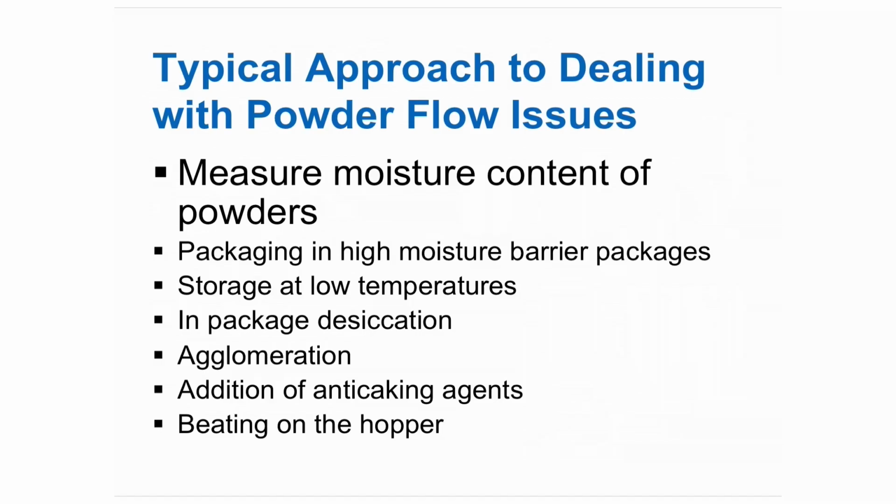You may store it at low temperatures, since again, keeping in mind the idea that it's moisture and temperature along with time that have the impact. So if you can store at low temperature, you could eliminate the temperature effect, but of course that can be costly as well, to have special storage conditions. You might include some sort of a desiccant in the package with the powder material that preferentially takes up the moisture and keeps it away from the powders that would start to cake and clump. And you can do this also with anti-caking agents that are hygroscopic and able to incorporate and bring in moisture without having subsequent large impacts on water activity.